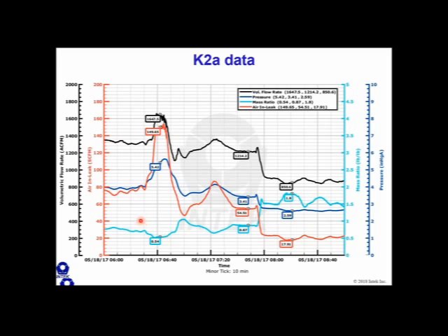So, okay, I'm starting to see answers come in now. So you can see here, yeah, it's an air in-leakage problem. The air in-leakage is quite high here, 80 SCFM. Water to air mass ratio is low. They definitely have excess back pressure due to air in-leakage.